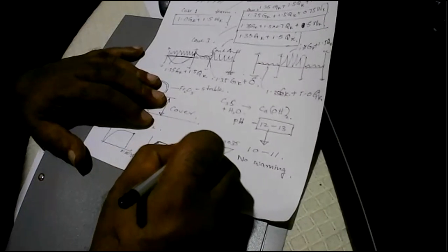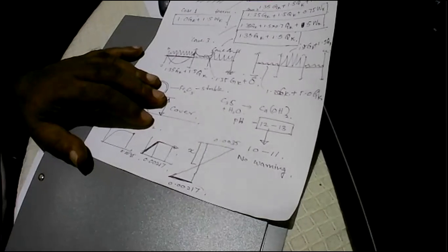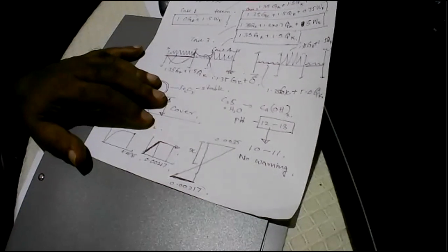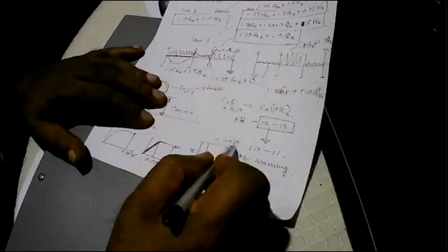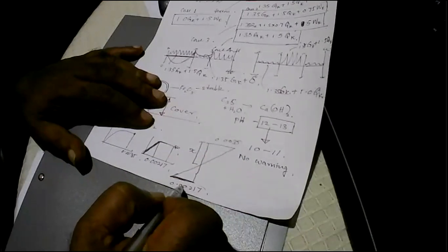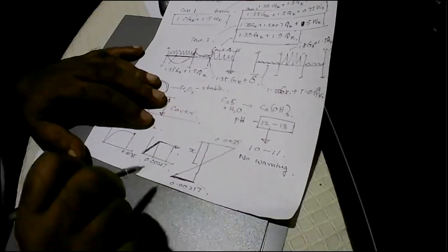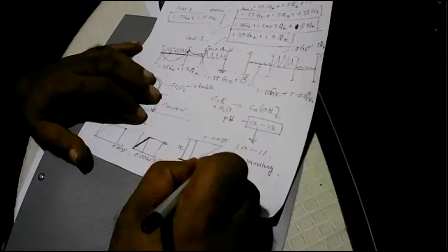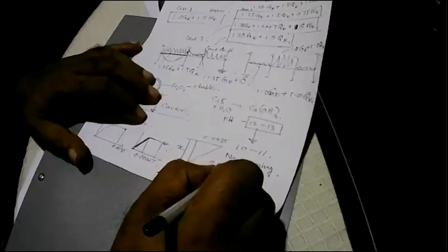So we like to see what the depth to the neutral axis is when this is going to happen, so that we can put a limit on the neutral axis to ensure that when the concrete strain is 0.0035, the steel strain will be more than 0.00217.